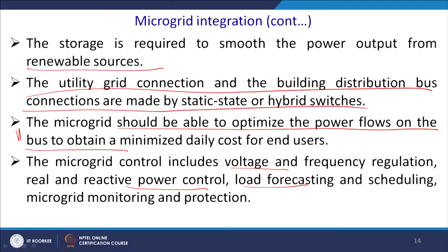That is something you forecast from the pattern of history. Then scheduling, because you want to change that particular pattern of behavior gradually with the consumers, so that you can try to match the peak of the generation and the load peak close to each other, so that the size of the storage element reduces,